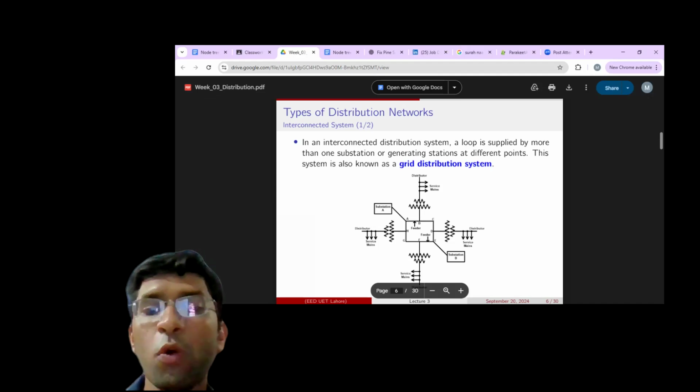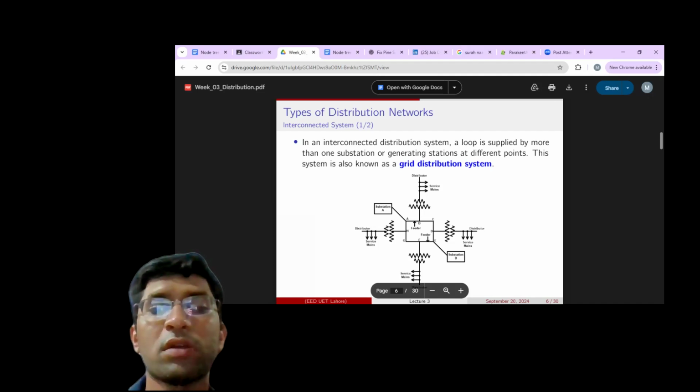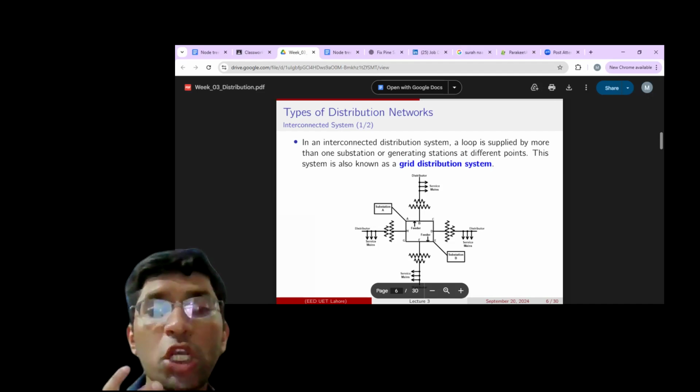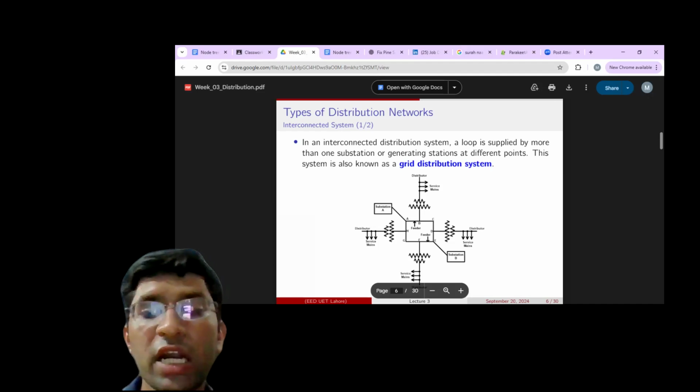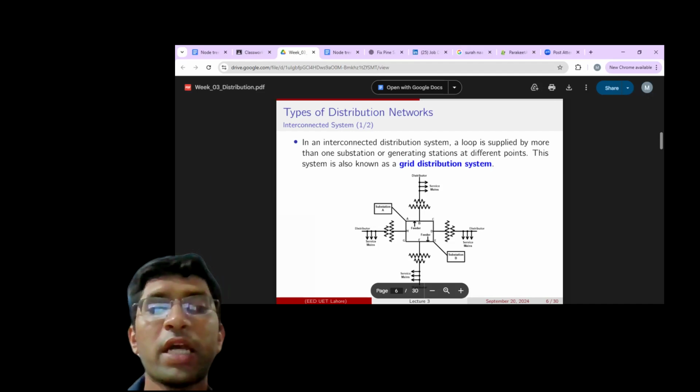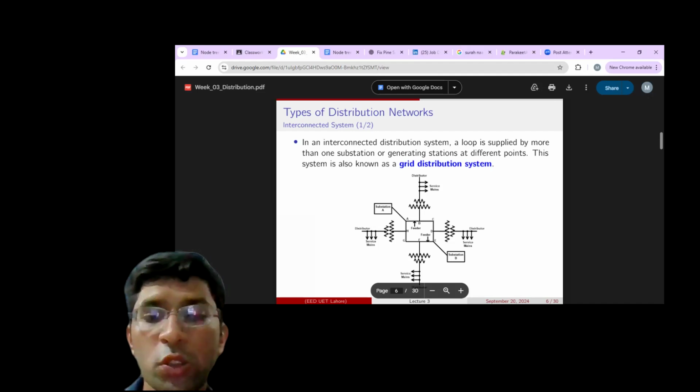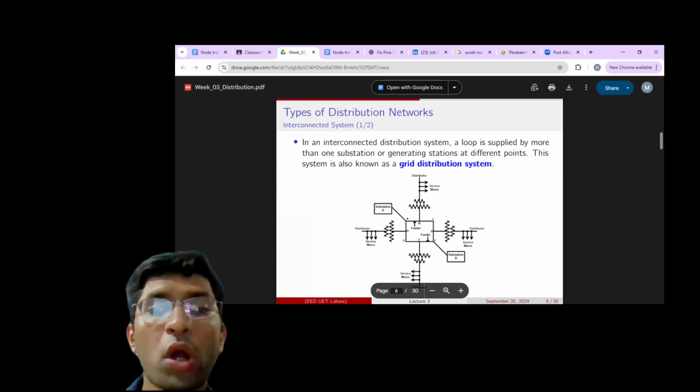So protection is more advanced. Directional relays, circuit breakers, and reclosers are used to isolate only the faulty section. You must have studied in your power system protection course about the relays. So most of the loop stays energized in this way, because circuit breakers, directional relays and reclosers are used to isolate the faulty section. So more security is provided.